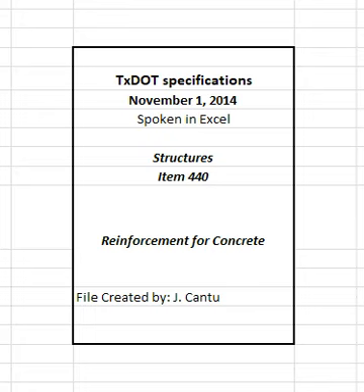Table 6. Minimum lap requirements for steel bar sizes through number 11. See table in specifications. Do not lap number 14 or number 18 bars. Lap spiral steel at least one turn. Splice WWR using a lap length that includes the overlap of at least 2 cross wires plus 2 inches on each sheet or roll. Splices using bars that develop equivalent strength and are lapped in accordance with Table 6 are permitted. Lap the existing longitudinal bars with the new bars as shown in Table 6 for box culvert extensions with less than 1 foot of fill. Lap at least 1 foot 0 inches for extensions with more than 1 foot of fill.